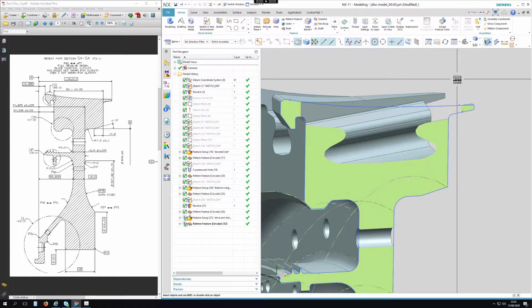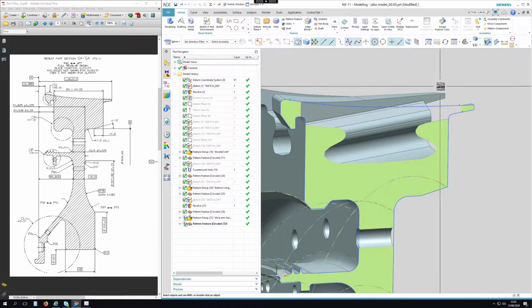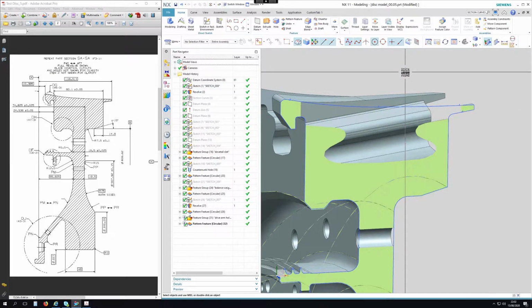Now, what you're better off to do is to bring these points into the drawing view. You don't want to be recreating these points in the drawing view and them not be associative. So these points are driving this sketch. So we want to bring these points through into the actual drawing itself, because then you can't go wrong when you're dimensioning them up.